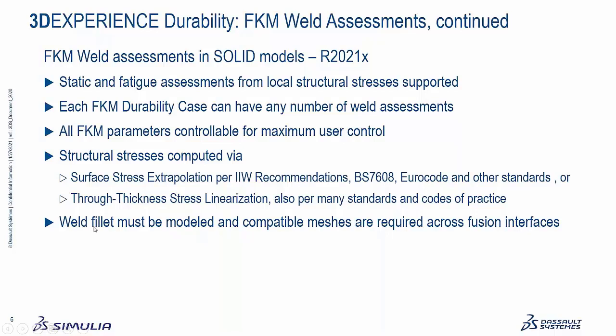You do have to model the weld fillet in the CAD model, and you are required to make compatible meshes across the interface between the weld and the plates being welded, in other words, across the fusion interfaces.